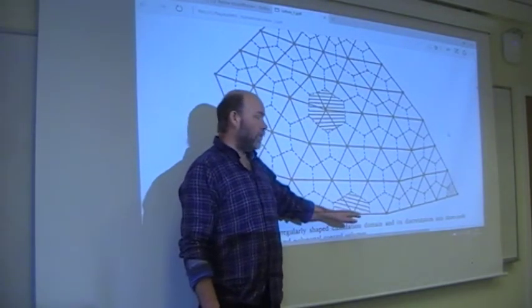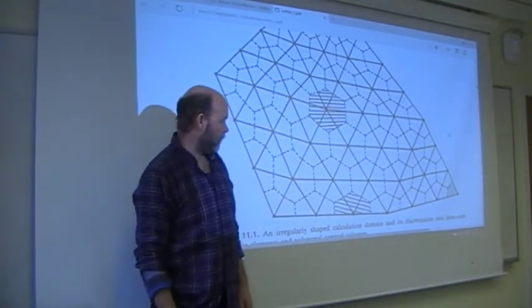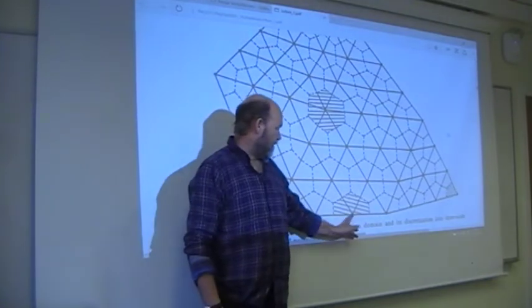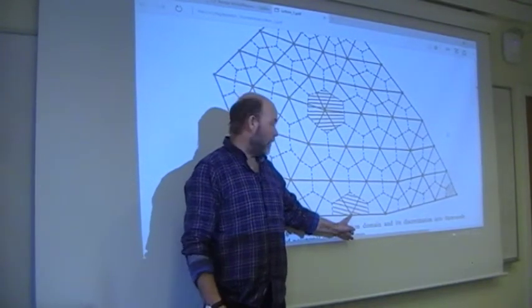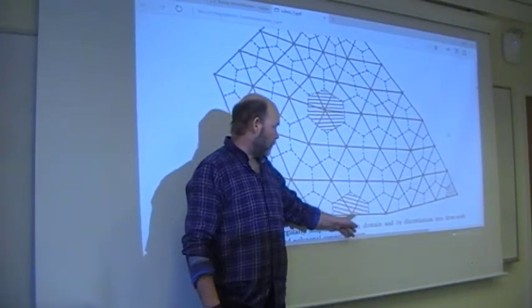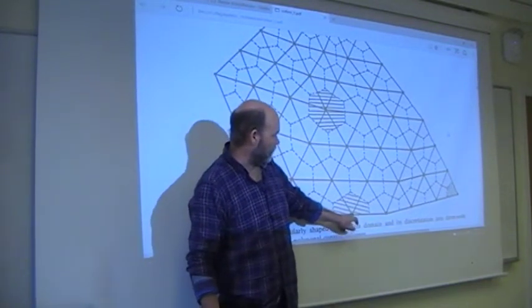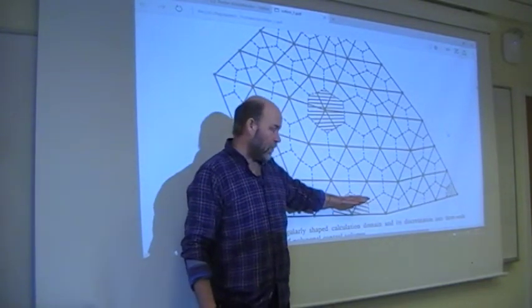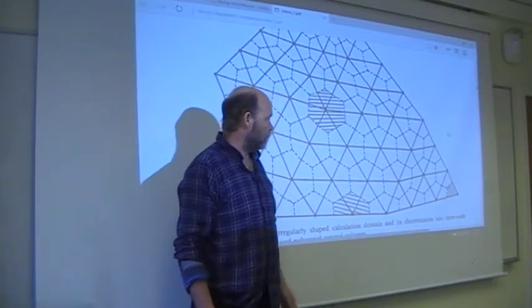So if you don't do anything, automatically you will get Neumann condition on the outlet. So that was sort of cute. Of course, if this one is Dirichlet condition, so you know the value there, then it's not a problem. Then you just insert a number, and you don't treat it as an unknown. But if you treat it as an unknown, and if you don't do anything in particular, you will get the Neumann condition.